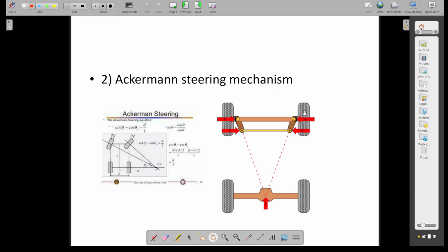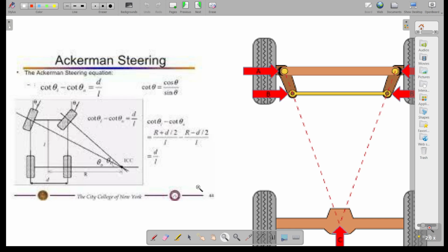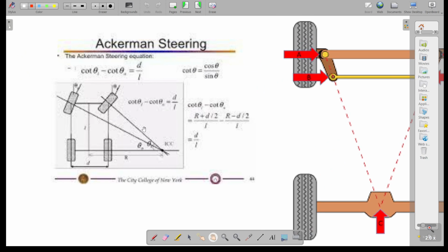You have the four wheels here, wheels 1, 2, 3 and 4. I already told you that when they are turning, the arcs they follow should have a common center. When this condition is fulfilled, we say that we have the steering condition for the steering mechanism.